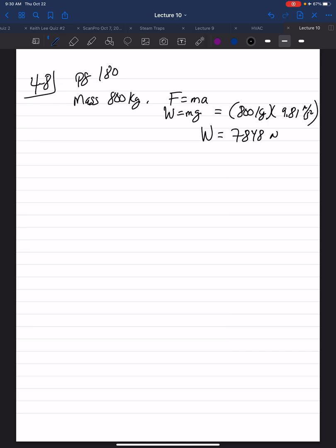All right. Next, the problem says the center of mass is located at G. So that is where that weight is applied. They give you F is 15 kilonewtons, which is the weight hanging off the hook there. The bearing at A only has a horizontal force, and the bearing at B has both horizontal and vertical components. So those are our two support reactions.